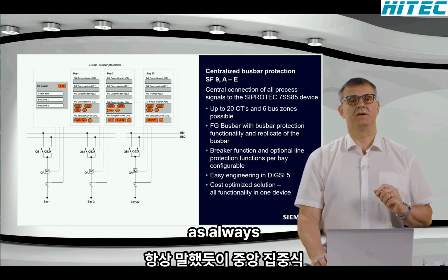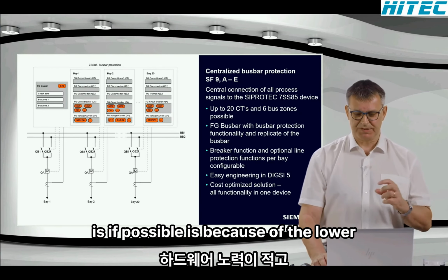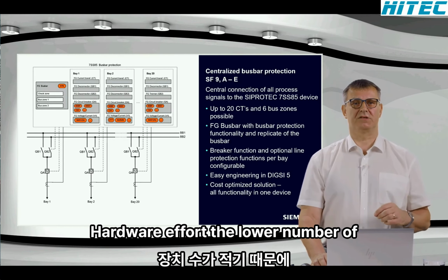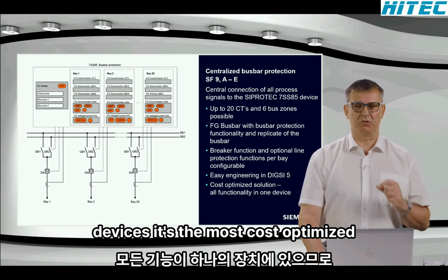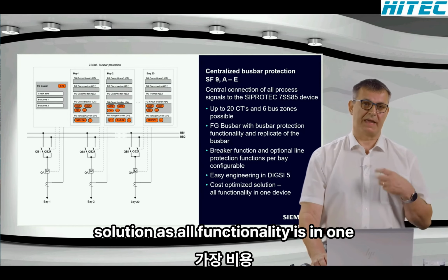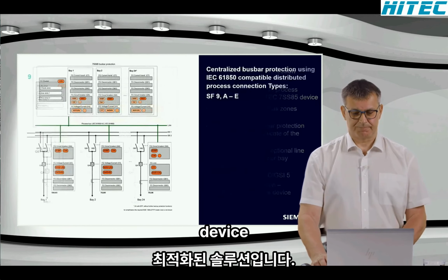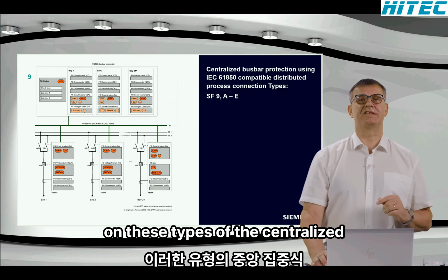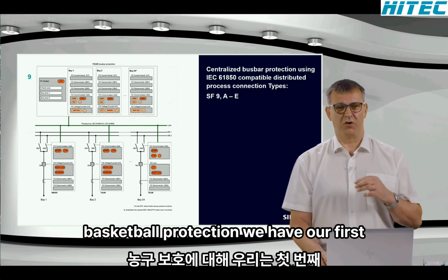As always, the centralized busbar protection is, if possible, because of the lower hardware effort and the lower number of devices, the most cost-optimized solution, as all functionality is in one device. Based on this type of centralized busbar protection, we have our first